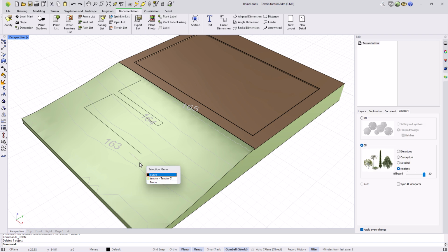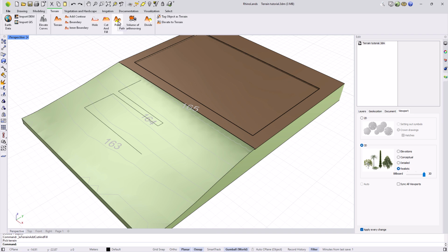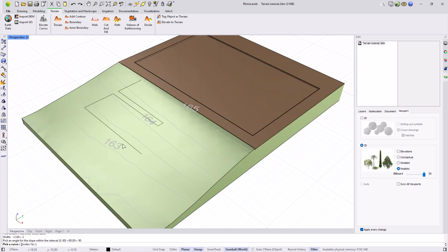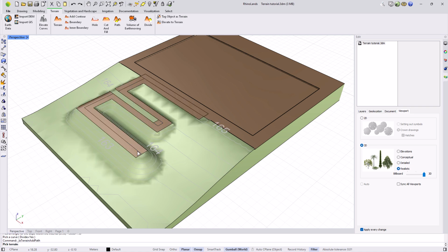I'm going to divide this value of 1.92 by 4 sloped sections, which gives me a height of 0.48 per section. Now, when I generate the earth movement with the Path command, I set a width of 2 meters, and in the command bar, if we're not interested in creating the terrain division, I can turn that off directly before selecting the curve.